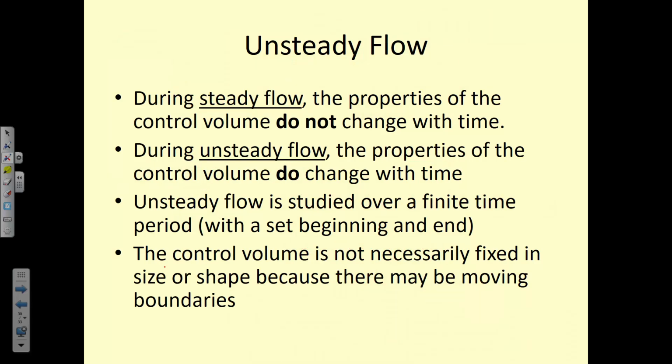Okay, unsteady flow gets a little bit more complicated because now the properties of the control volume do change with time. So mass can be accumulated or drained, energy can be accumulated or drained, the properties are changing. Usually we study it over a finite time period. We say, okay, initially it's this, at the final state it's this, we have some interval over which we're studying. Steady flow devices, you can say, okay, this is steady state operating conditions. What are the properties at the inlet or the outlet under steady state? It doesn't matter the time period so long as it's operating under steady state.